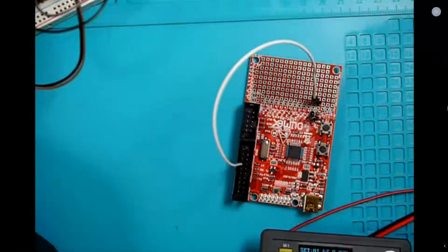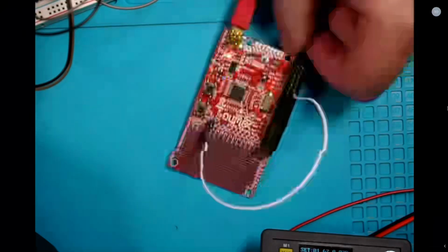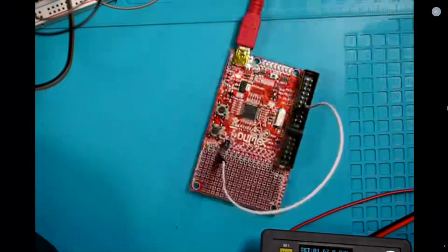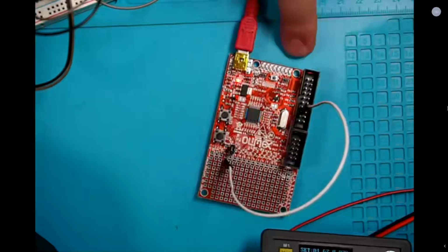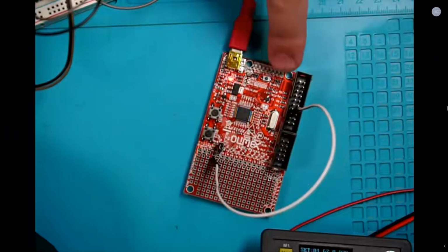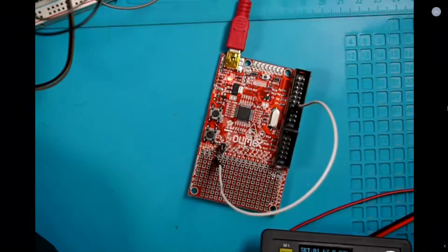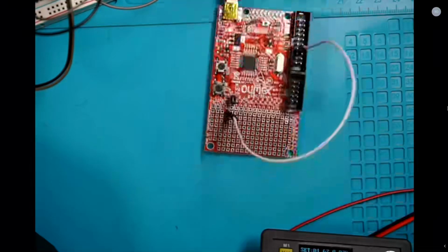We can test it by connecting it to power again, and also setting the jumper. So we can see now it's in bootloader mode. How do I know? Because the default firmware that's currently on the board, which would normally run, would toggle the LEDs. So that's not happening. So we know we're probably in the bootloader.